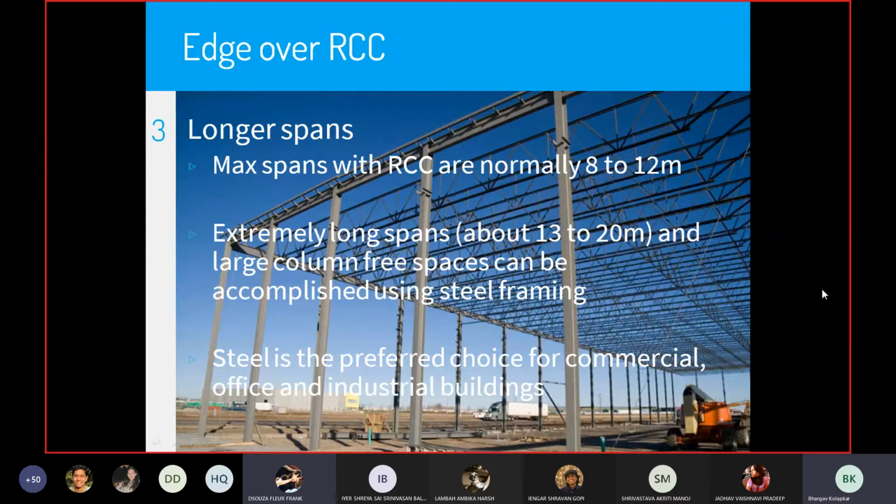But would that increase the cost of the building a lot, to have columns completely in steel? It depends on what you want to save your cost on. If you're getting a larger floor space, a lighter foundation, or if steel improves the overall behavior of the structure, and overall it gives you a lesser number in terms of cost or time as compared to concrete, then it's a decision that involves all these studies. But we cannot just say that if you're using steel in columns it is an expensive structure. I think it's not how we can put it.